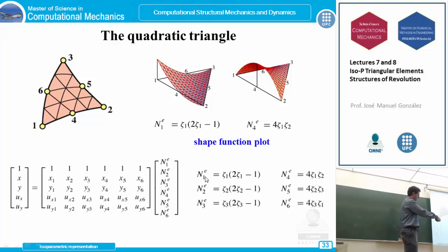So we need a normalization factor of 2 in this shape function, and now for this node we get a 1 here, with this expression. So the idea is the same idea we used in the quadrilateral elements, that is, vanishing the shape functions in the opposite sides, and using this idea we get the shape functions for these 3 corner nodes in this way.